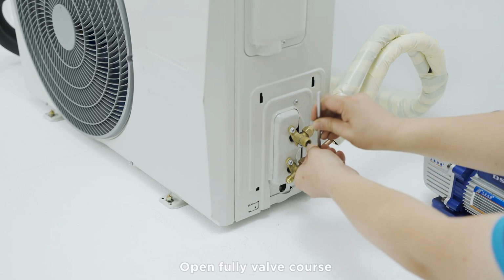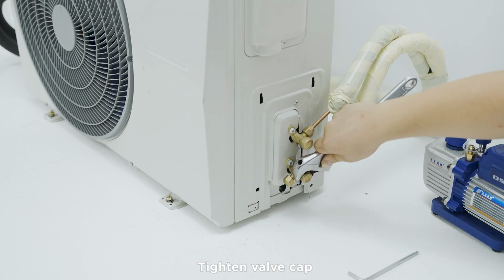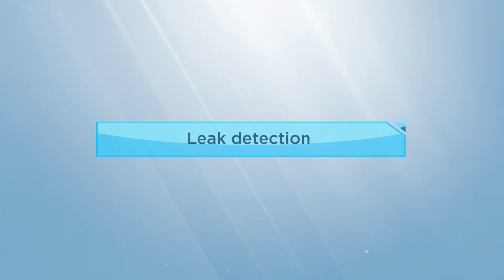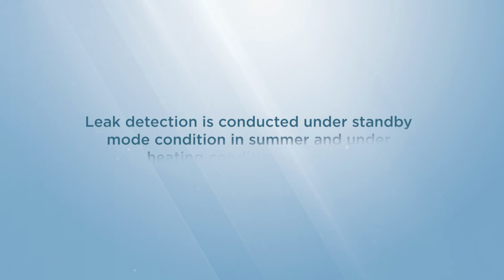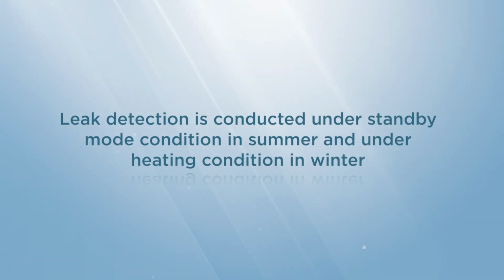Open fully the valve cores of the high pressure valve and low pressure valve. Tighten the valve caps. Leak detection. Leak detection is conducted under standby mode condition in summer and under heating condition in winter.